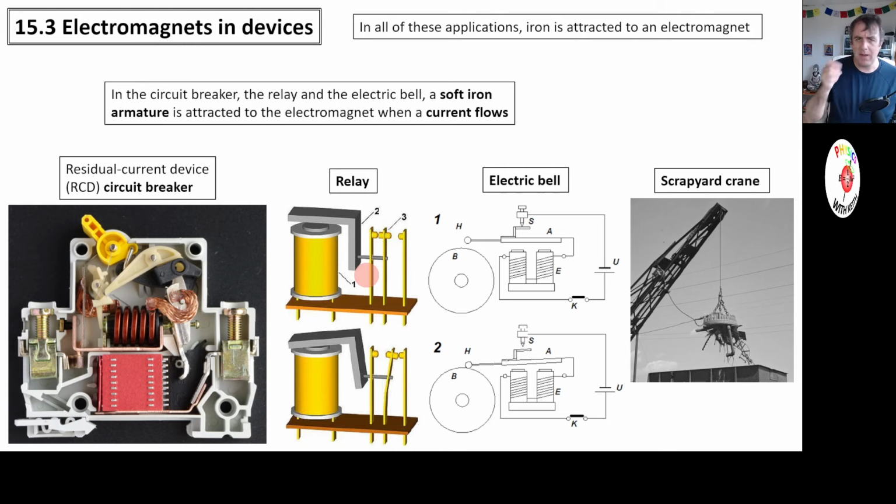It uses a three-phase power supply. It's huge grills. So there must be some way of switching off the grill platen when the temperature reaches the right amount and switching it back on again when the temperature drops to maintain the temperature of the grill platen. So there are sensors, and those sensors feed information to what they called a computer, which would decide whether to switch on or off the grill platen to maintain that temperature of 177 on the bottom, 218 on the top.